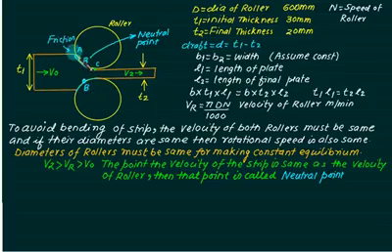Now from A to B, the velocity at point A is V0 and the velocity at point B is VR. So VR is more as compared to V0. Because of this, the strip is drawn inside because of friction. Afterwards, V2 is more than the velocity at point B, the neutral point. So the strip is automatically dragged because of the high velocity. We don't want friction over the entire passage, just friction for the A to B portion. That's all. Once the strip has entered, it automatically comes inside.